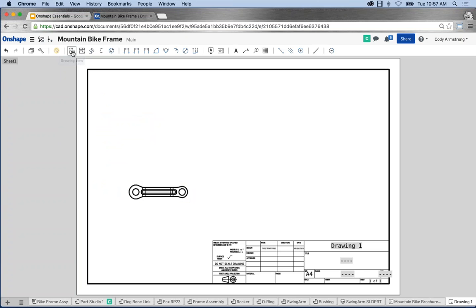Now I can go back to the standard drawing views and insert a top or a right or an isometric, but you can also do this, of course, by projecting views. So I can select projected view, left click, and move my view up to create a top view. Do another one, projected view, left click, create a right view, and then left click also to create a projected view. Okay. So inserting basic views, very simple.